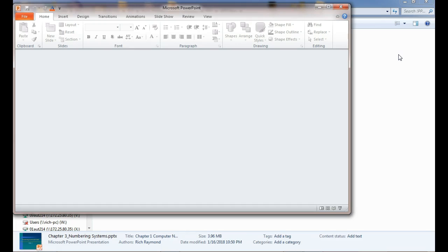So what you'll do in this class is, if you need a NAND, you will AND it and then invert the answer. So it'll take two instructions to do a NAND. We don't have an exclusive NOR because we can do an exclusive OR and then just complement the results, right? You understand? And we'll see how to do that.